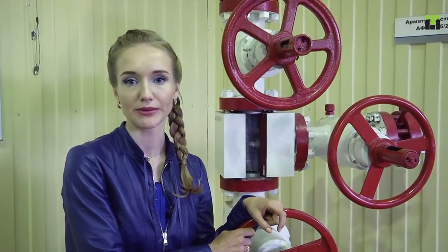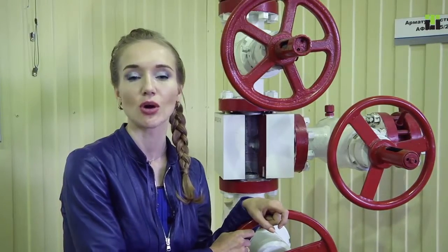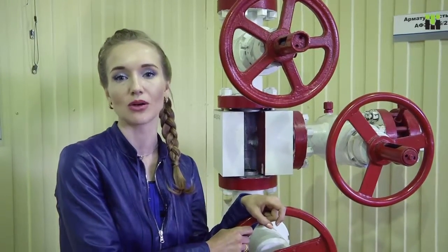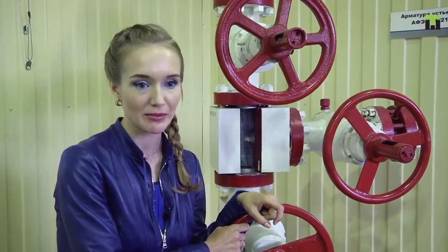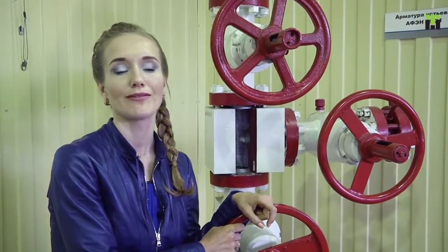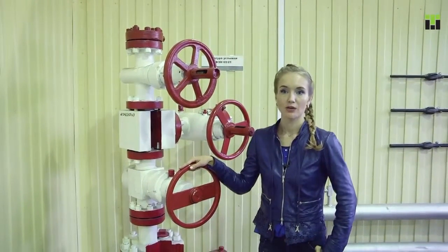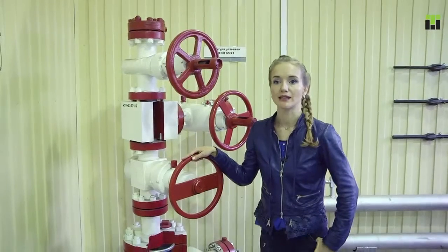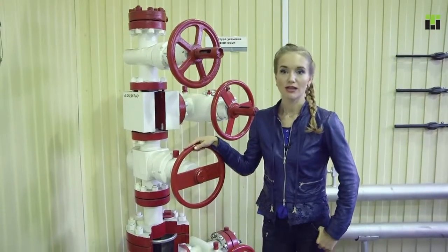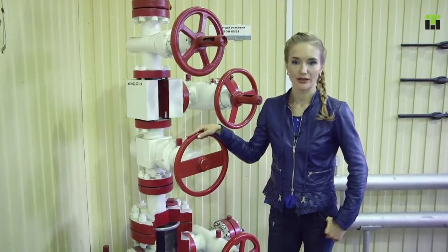Such chokes are made of wear-proof material and the orifice has a specific diameter which will determine how much oil will be flowing out of the well. The diameter may vary from 3 to 15 millimeters or above 15. Sometimes bottom hole chokes are used, which can be faster placed and adjusted. Such chokes are installed on flow strings at any depth, supported by packers.